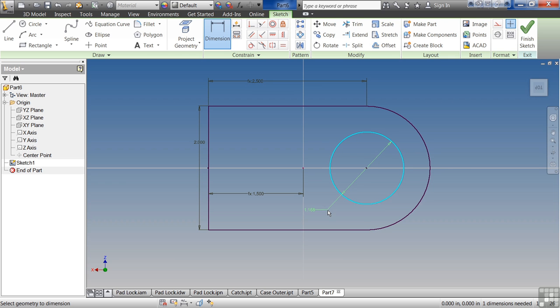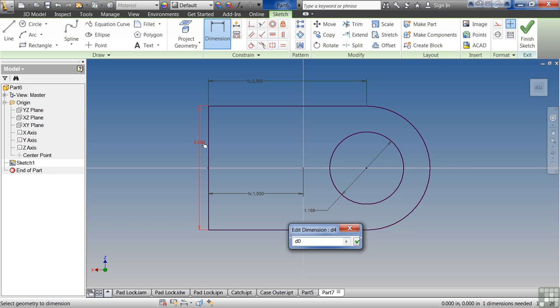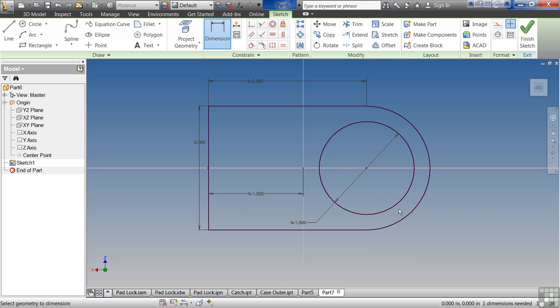Then I select my circle. So my circle is 2 dimension minus 0.5. What that does is it leaves me a 1/4 inch all the way around so that if my dimension here changes, my circle will always be a 1/2 inch around the outside. Right now my sketch is fully constrained. This is what I want. I like to see it black, meaning that everything is locked down the way it should be. I'll select line, hit the green dot, right click and hit OK to finish.